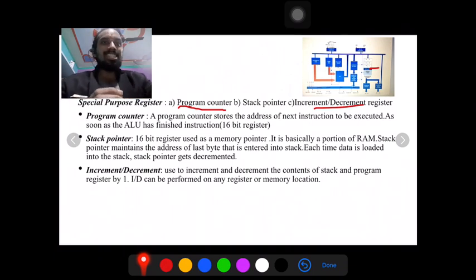Its L2 cache is somewhere around 1 MB and its clock is 1.7 GHz. If you increase it, it can go up to 2.7 GHz. So how powerful is this. It is used in the avionics industry for flight computers. One more thing, usually this company gives around 10 to 15 years of lifetime. But when it comes to aircraft, you need another 10 to 20 years. So they deal with the manufacturer, and they specially design it for avionic systems.